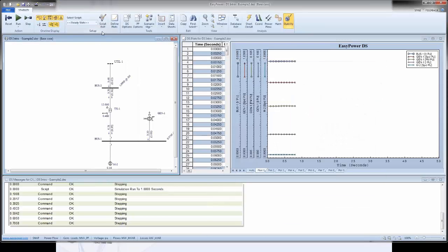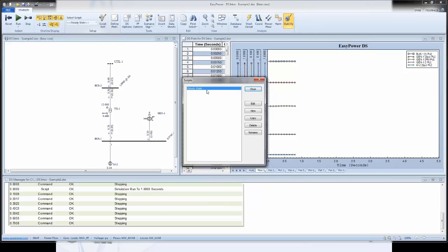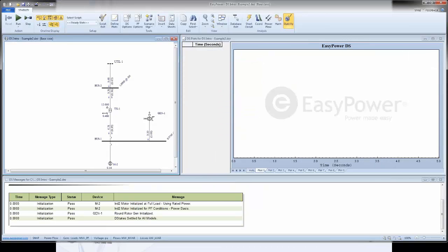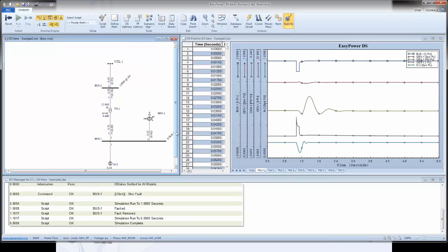the script here. So what you saw was one option of defining different events in EasyPower. The other option is that you can double click on a bus. Double clicking on different elements would make different sense, and would create different consequences. Let's say you double click on a bus, it always means a short circuit. You put a fault there.